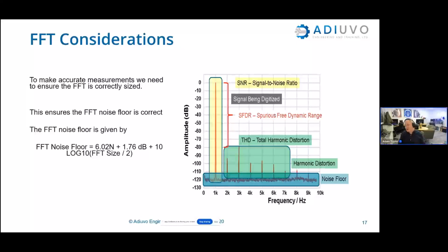One of the cool things we can do, and one of the reasons why FPGAs get used so much in this application, is we can use the FPGA to capture data, or, if we're using a DAC, we can use it to generate waveforms that can be output and captured on a spectrum analyzer to do the same thing.